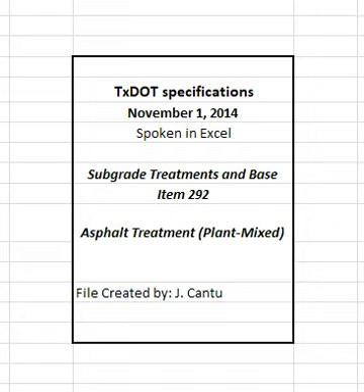Table 1. Aggregate quality requirements. Property and test method and specification requirement. See table in specifications. 1. Use only when shown on the plans, instead of wet ball mill test. 2. Required only for reclaimed asphalt pavement, RAP, stockpiles and recycled aggregates when more than 30% RAP is allowed.